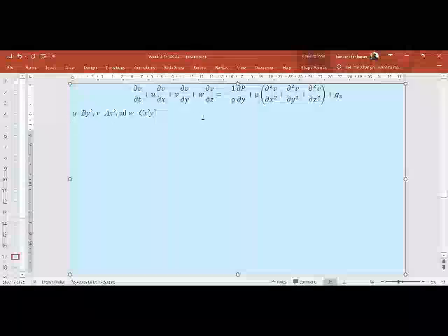We have to find out the pressure gradient in the y direction. Therefore, we need ∂v/∂t. Now again, as you can see here, just take this term. This will go to 0. We know that this term goes to 0. U times ∂v/∂x, this term exists. V times ∂v/∂y: we see that v is not a function of y, so this term goes to 0.